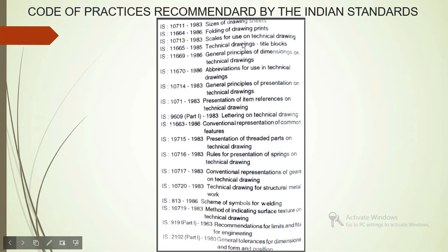The title block information standard is available in Indian standard 11665. General principles of dimensioning methods used in technical drawing are available in Indian standard 11669.